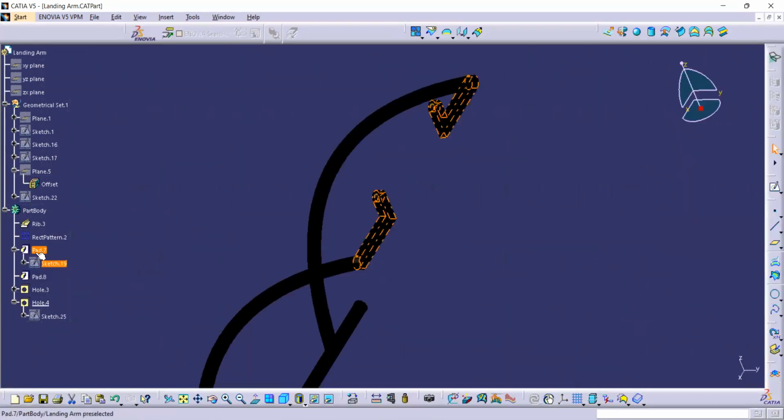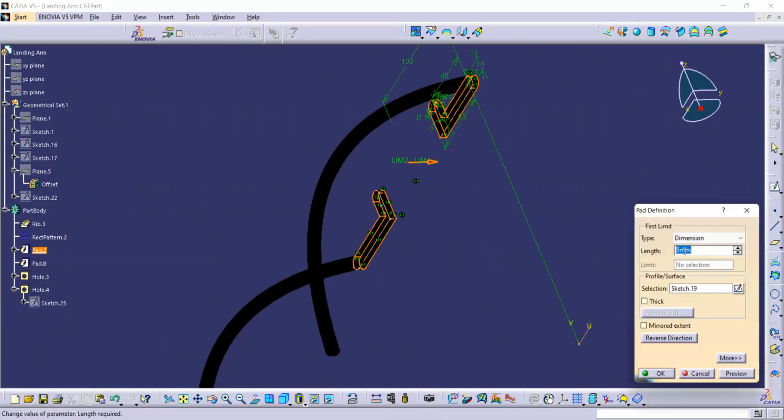After that, we are going to give it a pad of 5 mm. 5 mm is the maximum pad we can give for parts that are going to be connected with other parts. This is because this part will be 5 mm and the other part, which is in the hub, will also be 5 mm, and together it would be 10. And our design bolts are a little bit bigger than 10 mm, so we cannot make this bigger.